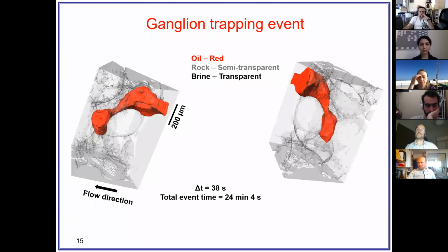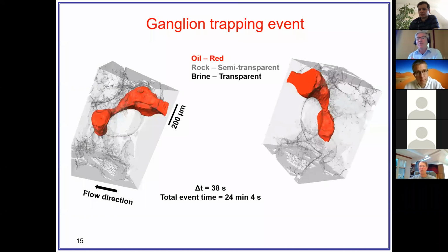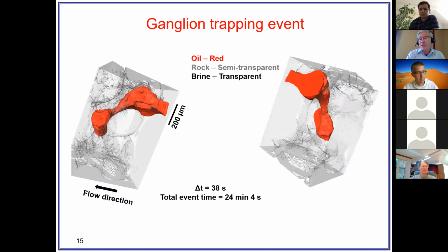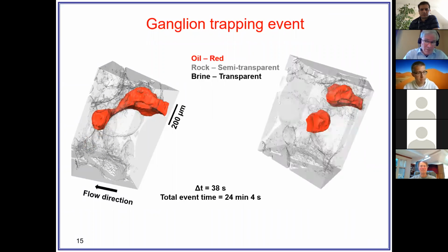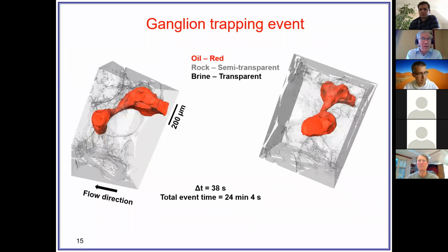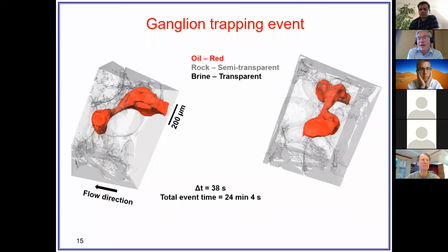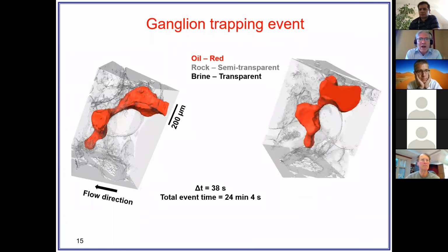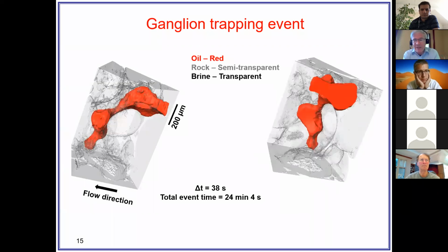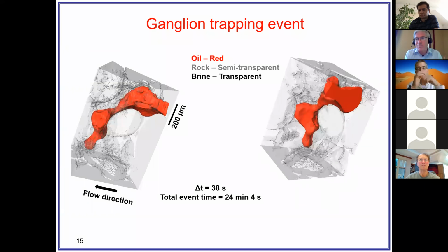cases, we've taken care that there is not asphaltene precipitation during the experiment. We can quantify that by actually measuring the wettability. However, we have done some experiments in our lab with asphaltene precipitation, so we've actually induced it. And yes, in those cases, you do see a wettability change. And obviously, you can clog the pore space as well, so you see a change in permeability. In the experiments I've shown, we're pretty confident that nothing untoward is happening. But you can actually induce that in the experiments, and you can use that to analyze the pore-scale effects.